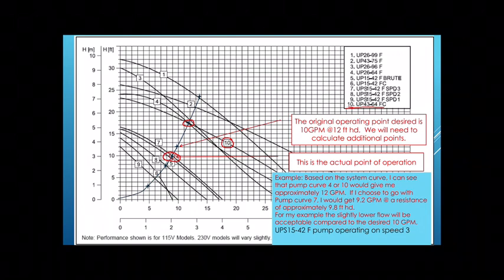But whether you chose 10 or 4, you would have had exactly the same flow rate, GPM, the whole thing would have been identical. And of course, that would have given you more flow, maybe 11.7 GPM, but you would have been working against roughly 17.5 feet of head is what you'd have been running on there.